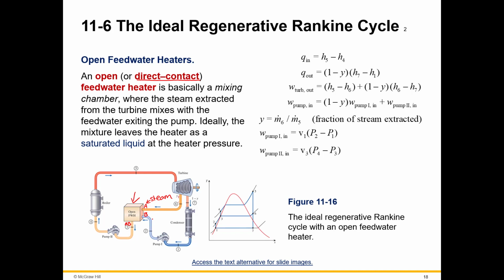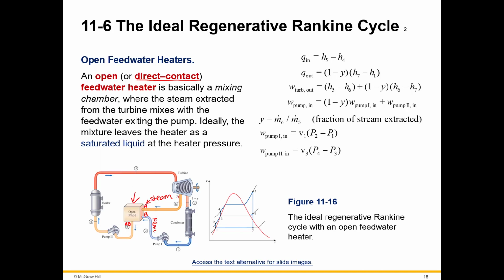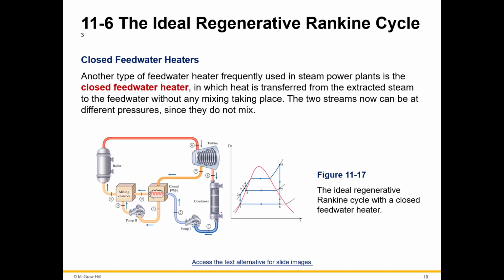So you here see the pump. I'm going to do feed water. Let's see if I can write sideways without pressing buttons, apparently. Okay. Ideally, the mixture leaves the heater as a saturated liquid at the heater pressure. And so then it leaves here at saturated. Ideally, right? And then here are those formulas to associate with those. And then you can see it here on a TS diagram as well.